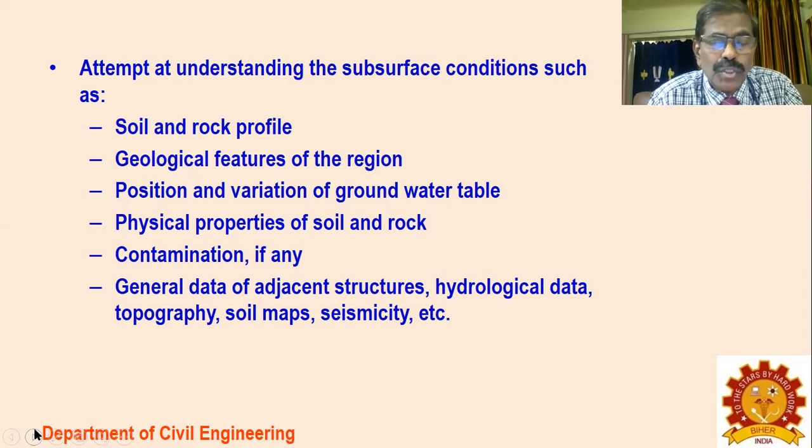Physical properties of the soil and rock, you have to take the test samples. Contaminations, if any, so you have to take the sampling waters and then test it in the laboratory. Then general data adjacent to the structure, hydrological data, topography data, and soil map, seismicity, etc. All those things, one by one, you need to understand when you go for the soil explorations.